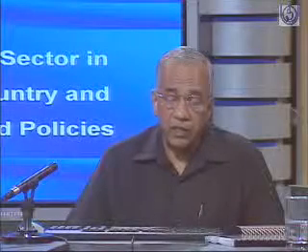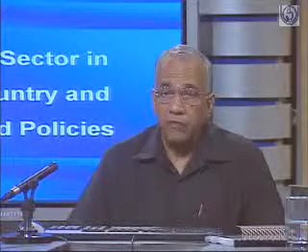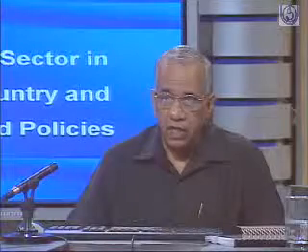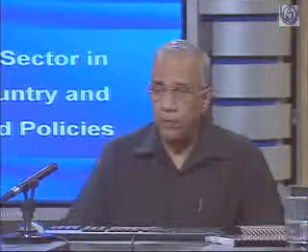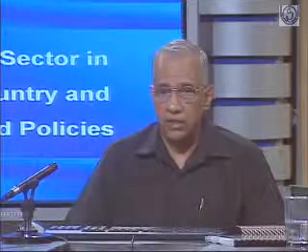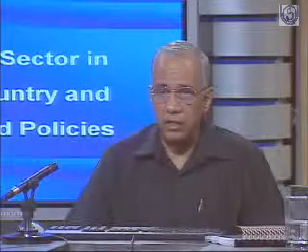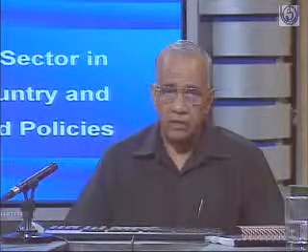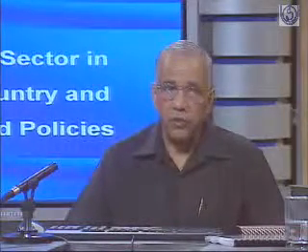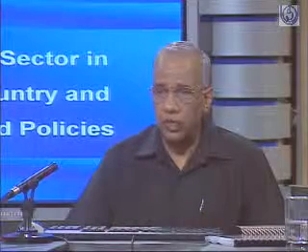Slowly we wanted to adopt this technology in our units, and the first units having features similar to supercritical units were adopted in the 500 megawatt sets at Talcher of NTPC. NTPC has a plant at Talcher in Orissa with 500 megawatt units. We adopted once-through boilers.